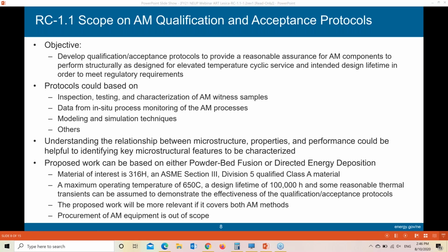So Drew, let me real briefly talk about the graphite for 1.2. The focus will be on mechanical properties, physical, if you will: modulus, stiffness modulus, strength, tensile, compressive, flexural. I would suspect that you're going to want to focus on tensile and compressive. They're probably a little easier to understand, and they will all be done at room temperature. There's no need to go in and get fancy and do any kind of elevated temperature at this point. We're looking for mechanisms, so keep it simple.